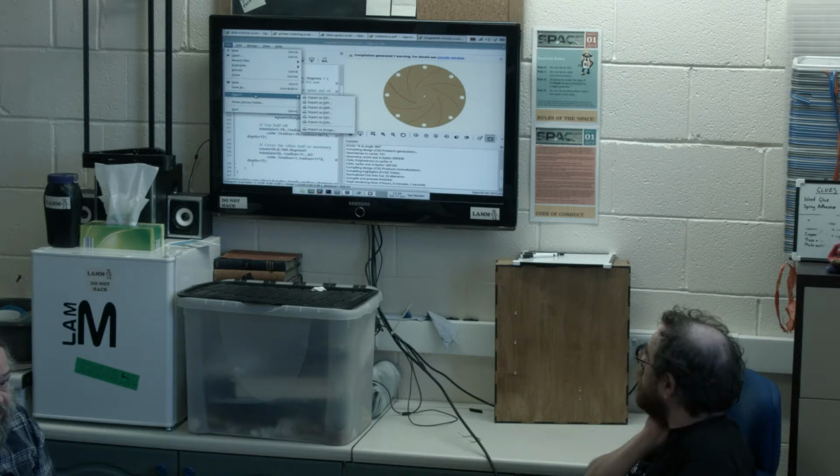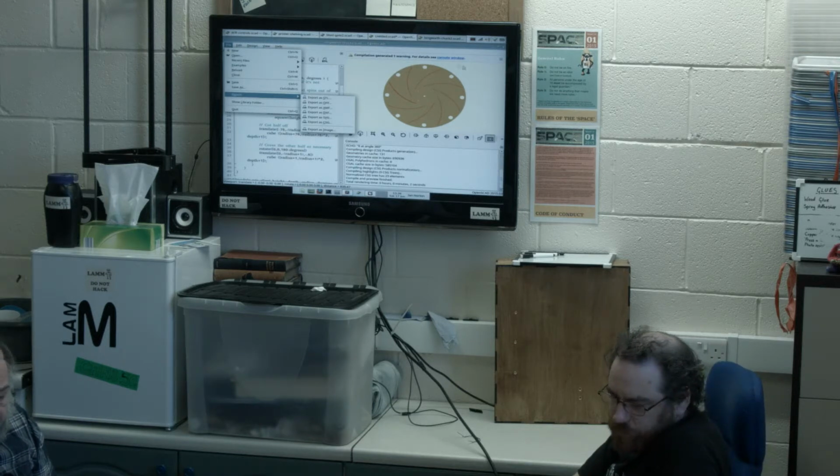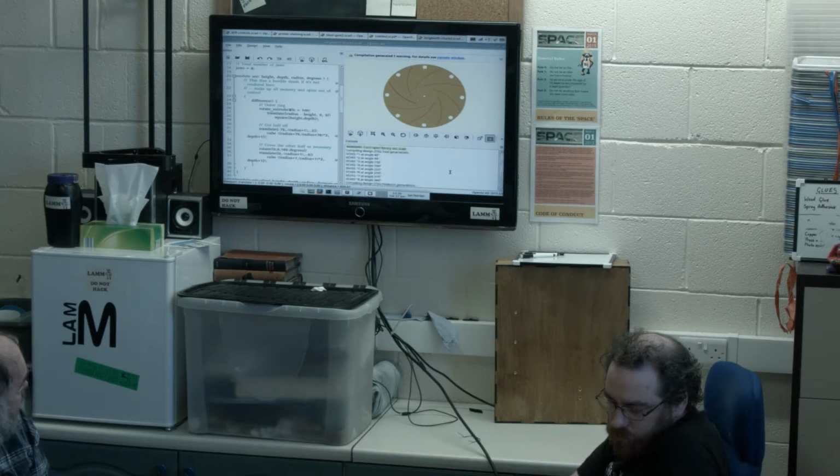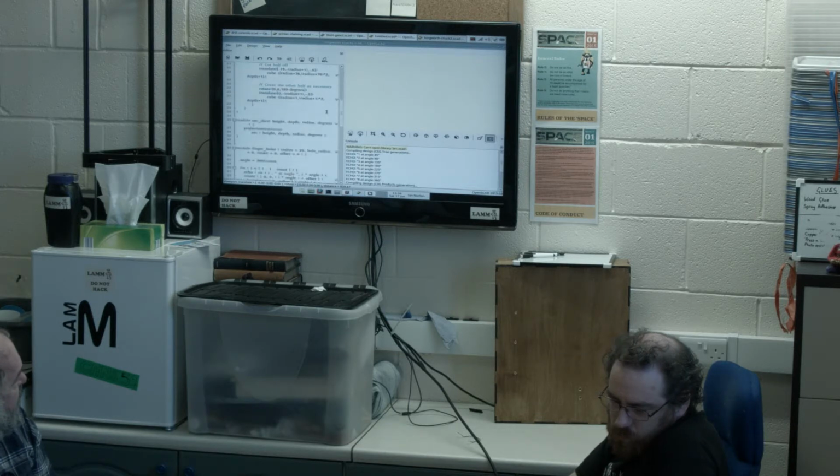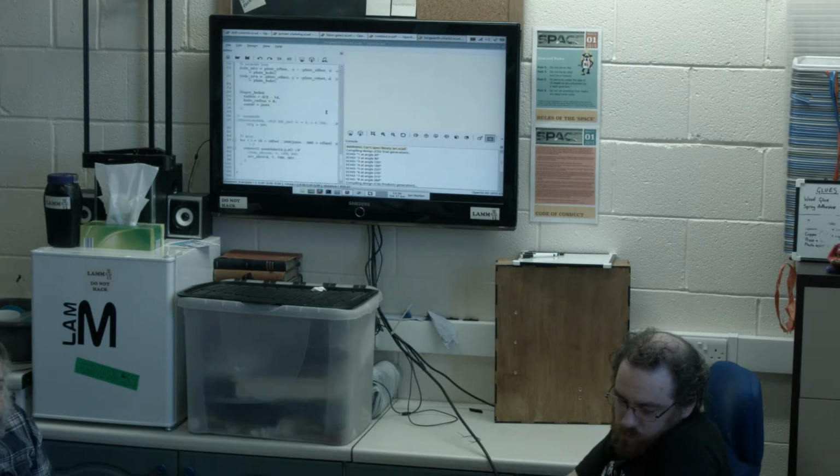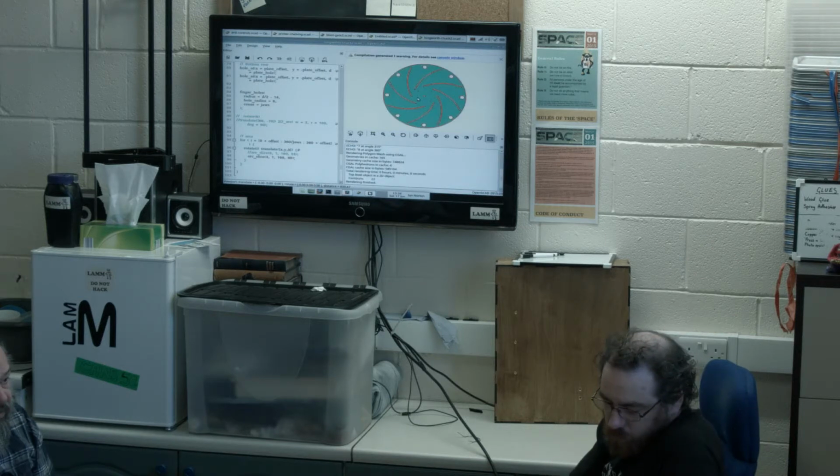I didn't go over that on Fusion actually. Does that apply to Inkscape? Inkscape has some issues. When you export to DXF, you have to specify which option you want, and even if you specify none of it, there's still both. They've got sizing issues in Inkscape and DXF and all that.